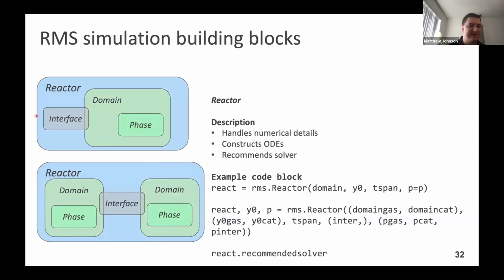And then we wrap the overall reactor object around the set of domains and interfaces, which figures out how to handle the numerical details, constructs the ODEs, and decides what's the best solver configuration, which is CVODE BDF. There are a couple of different ways you can configure CVODE BDF, especially handling preconditioning.